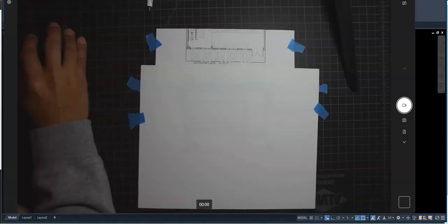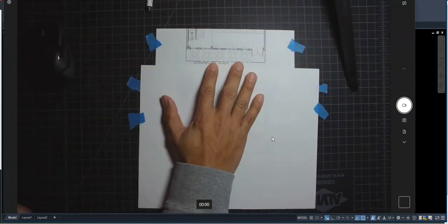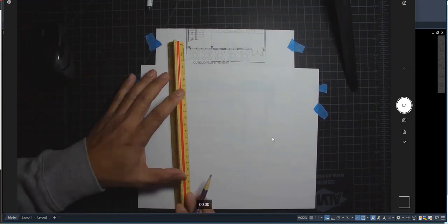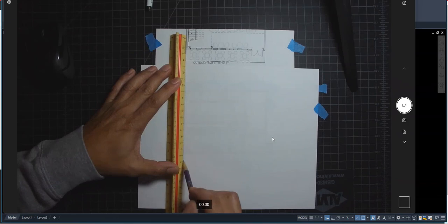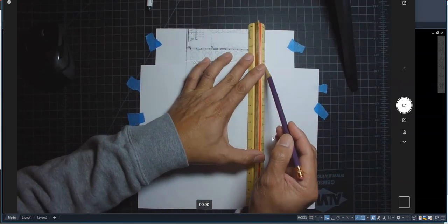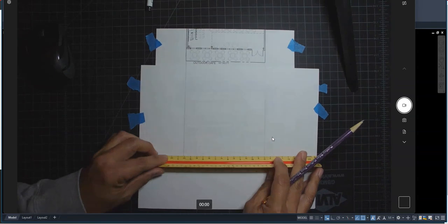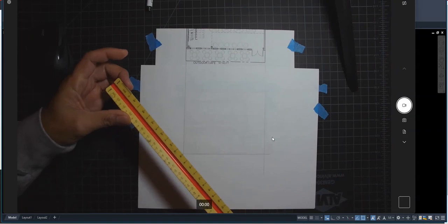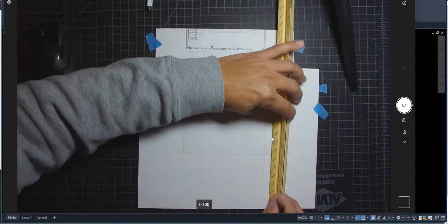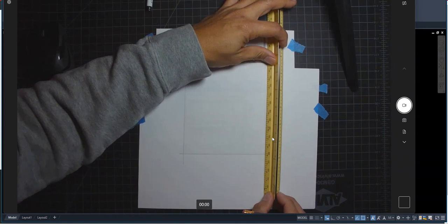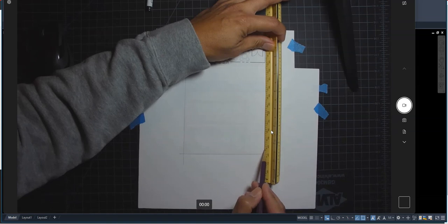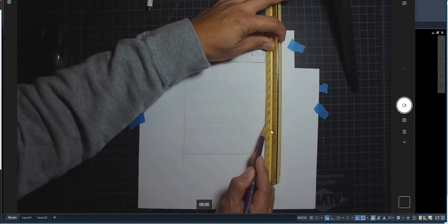And if you wanted to do that, you simply have to get your floor plan again, put a piece of paper, and then use a ruler again and project your 40 feet, project your ground floor, and then use your scale and find your 14 feet as you've mentioned before. I have 1, 2, 3, 4, 5, 6, 7, 8, 9, 10, 11, 12, 13, 14. So there's my 14. Okay.